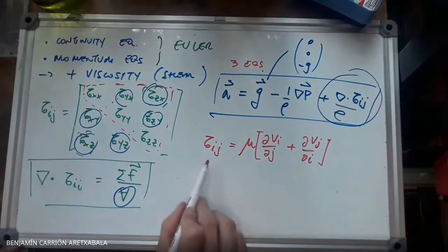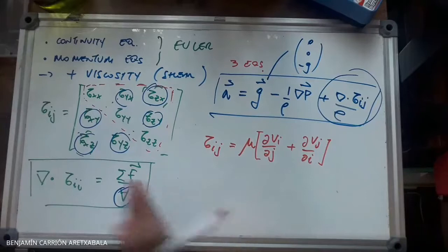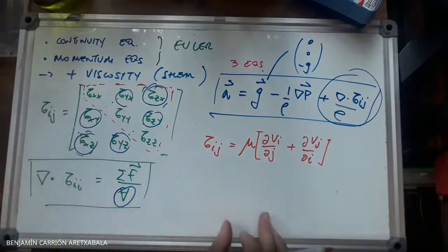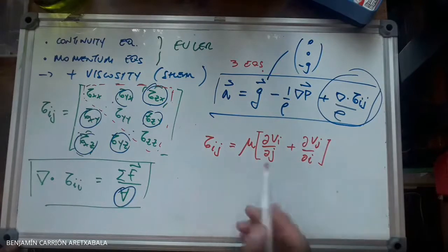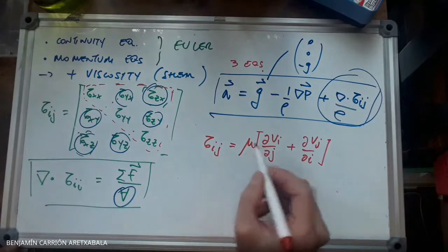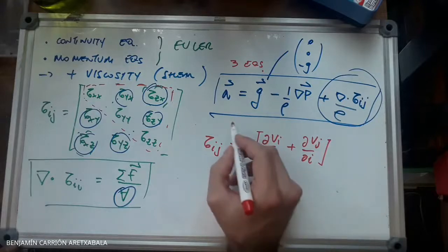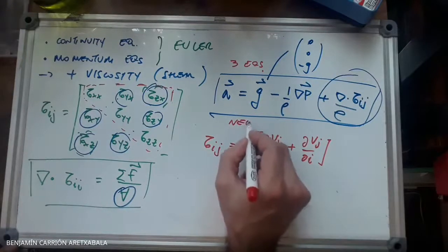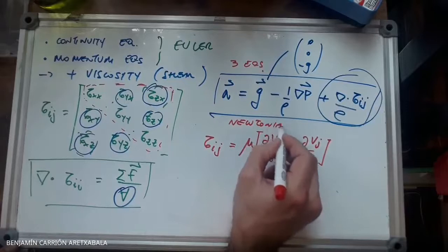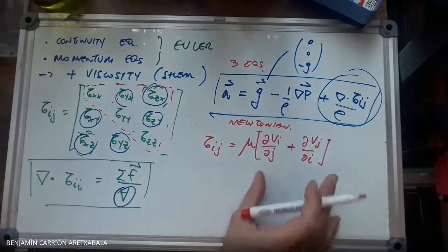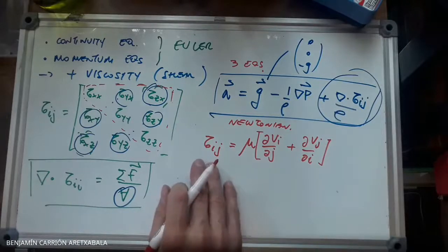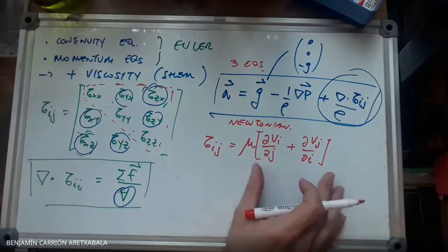Basically, on the same plane, you're going to have 2 shear stresses due to the motion of the fluid. Keep in mind that to do this, you need the fluid to be Newtonian. If it's not Newtonian, then you can't really relate your shear stresses with the gradients in velocity.